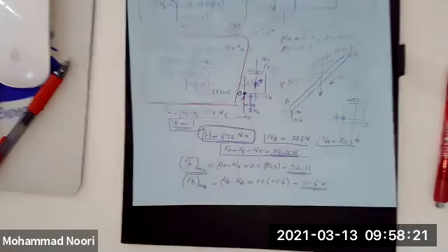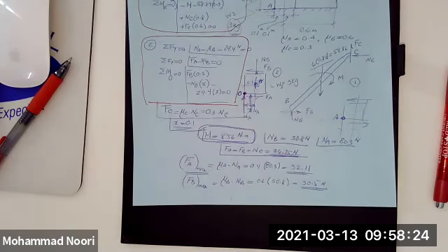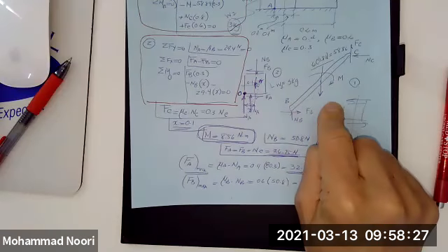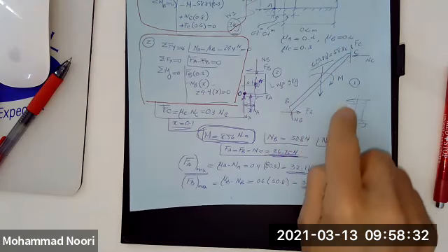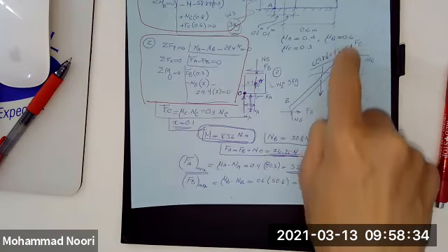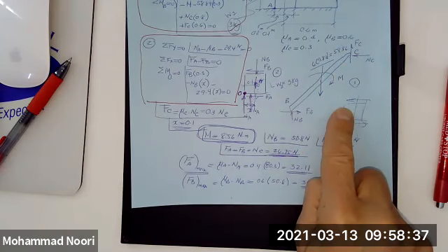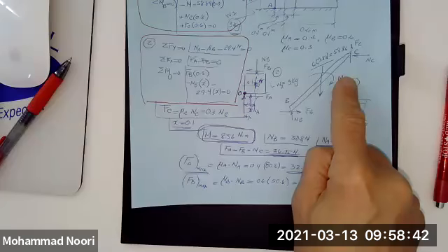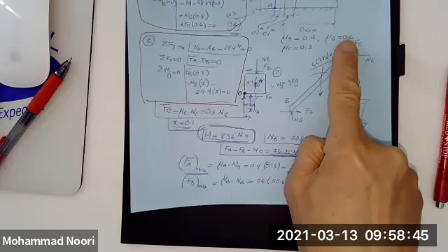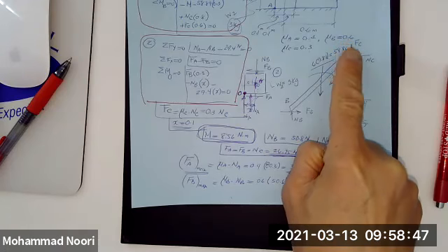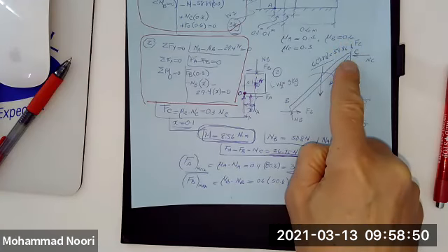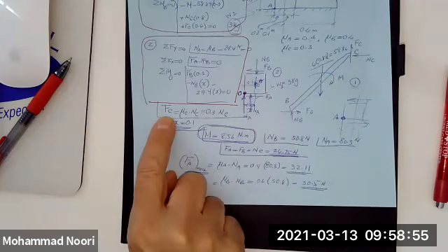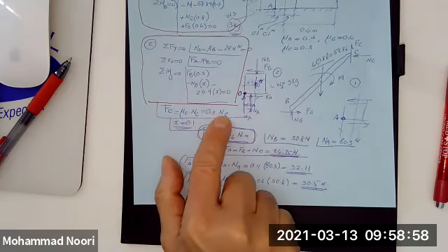Go back to the assumptions that the problem has given you. We're saying that if this moment is applied, the bar rod may slip against this wall. We do not want that to cause any slippage here or motion of the block, but it may slip here. In statics, the friction definition means you have a maximum friction force that develops here. So let's find that. That maximum friction force would be 0.3 times mc.